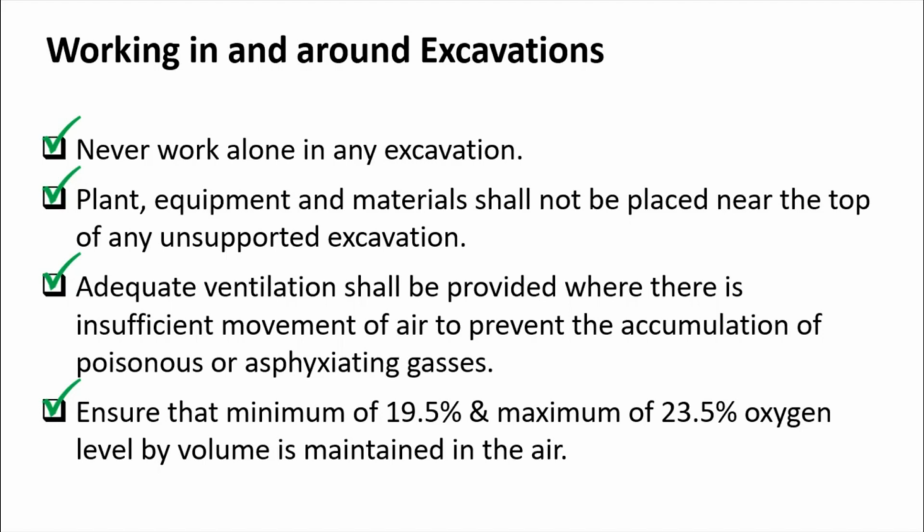And if the oxygen is more than 23.5%, the air becomes an explosive environment. So maintain the oxygen level inside the excavations only between 19.5 and 23.5%.